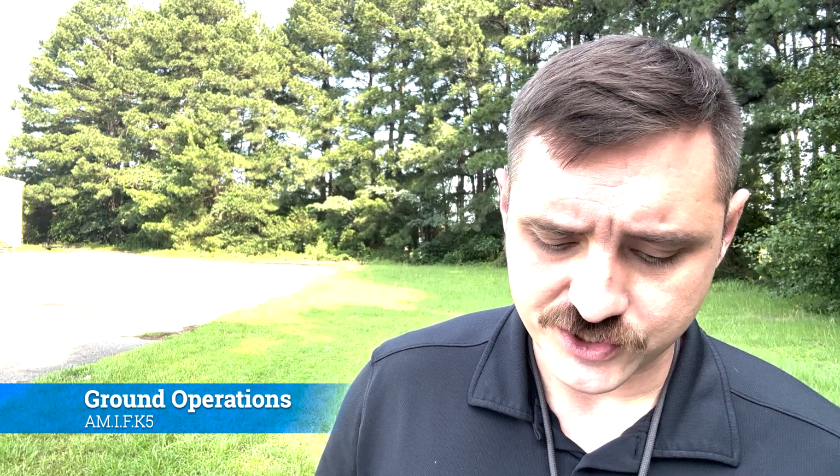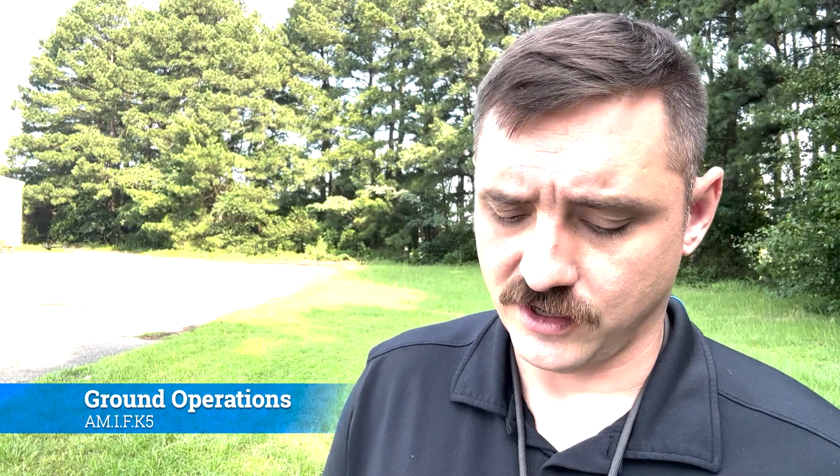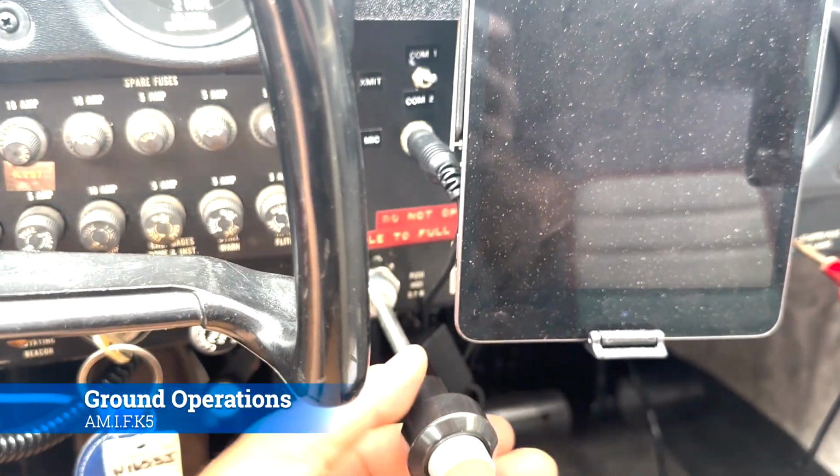Then you're going to place the mixture control to the position recommended for the engine and carburetor combination being started. Most of the time that's going to be full rich on the mixture. In a regular reciprocating engine, you just take the little red knob and go all the way forward. But it could be different depending on what engine you're working on, so always follow the checklist. Then you're going to open the throttle to a position that provides 1,000 to 1,200 RPM. On my airplane, you crank it about 3 times, which gives you about 3/4 of an inch of throttle. When it cranks, it always wants to go up high, so you end up having to throttle back to get to that 1,000 RPM range.